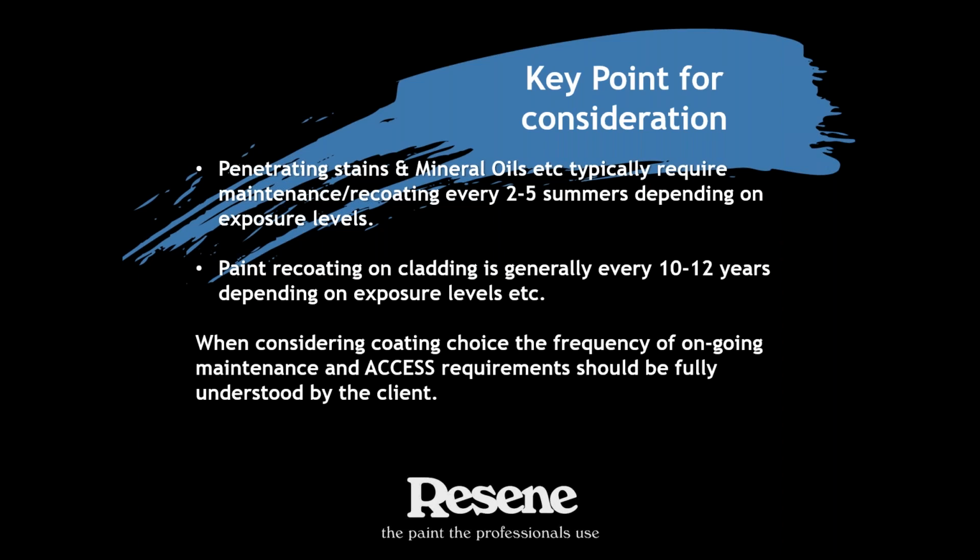If you have a multi-level residential dwelling or commercial building and it's stained, the access requirements to recoat can be quite significant. If you have to rescaffold a house, and we do field these calls regularly, where people are most upset that their 3-level house on the north face sitting in Northland somewhere exposed, that the stain requires restaining every couple of years, and they've got to bring in scaffold to do that. So there's a real expectation and understanding of what maintenance is going to be required when you're choosing your coatings for your properties.